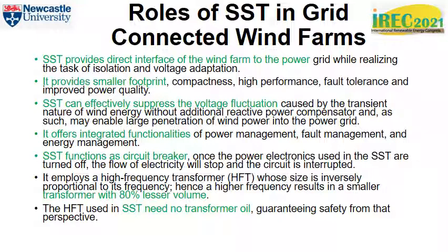Solid-state transformer employs a high-frequency transformer whose size is inversely proportional to its frequency. Hence, a higher frequency results in smaller transformer with 80% lesser volume. The high-frequency transformer used in solid-state transformer doesn't need any transformer oil, as such guaranteeing safety from that perspective.